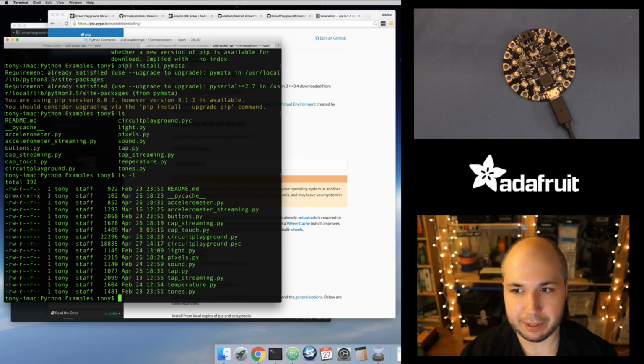You just have a Python object and you say change the color, or it has read the thermistor temperature, and it'll give you back the temperature in degrees Celsius, and you can use that and show it, or maybe change your actions based on that. So it does all the work of talking the Firmata protocol for you using that Pymata library.